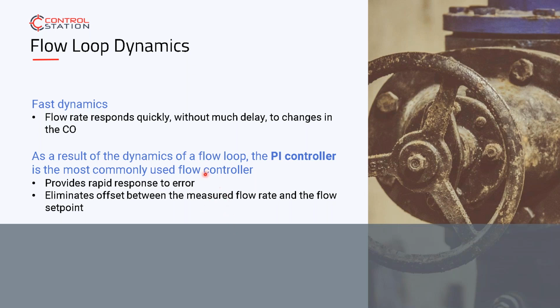And Brad, the one caution I would give is that just because you can doesn't mean you should. Because you have a fast acting flow process that can respond quickly, do you need to respond that quickly? That is the question I always ask people who are tuning, because if the process can change its position in 3 to 5 seconds, for example, or even 30 seconds, will your downstream process manage that rate of change?